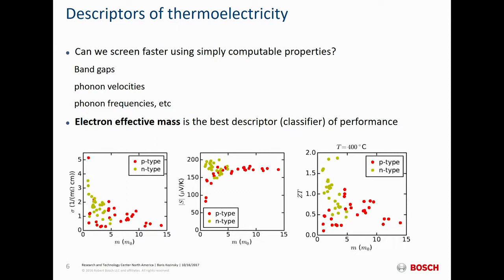And very briefly, here, what we found is that for all the materials we've computed, for all these tens and tens of Half-Heusler alloys in particular, the Seebeck coefficients at optimum concentration of electrons, basically at optimal doping, are all pretty much the same. So we couldn't really distinguish materials based on the Seebeck coefficients. They're all about 200 to, say, 175. What we did find interesting is that ZT in particular was mostly sensitive to the electron effective mass.